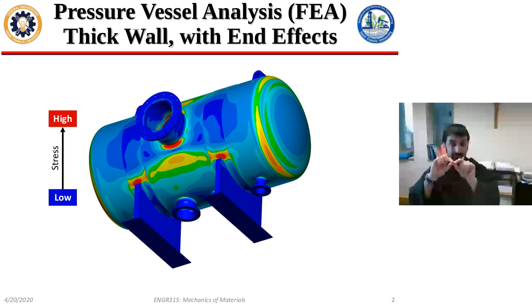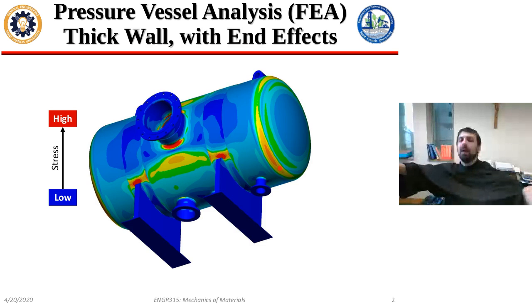Walls are thin, so a piece of sheet metal is really easy to bend. So the walls can't really be bending, and based on how we figure out shear stress distributions, it also means they can't support any shear stress. So we're going to ignore all that and say that there's only normal stress in the walls.